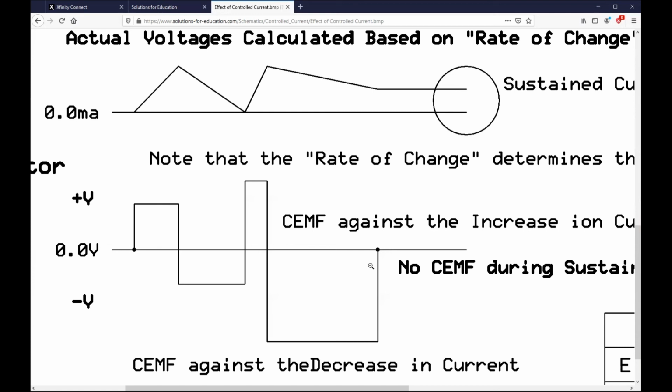There's some pinpoint or multiple pinpoints where it's a resistor for a tiny area on the aluminum, and the current flowing through there will heat up the inside of the capacitor, I squared R, and eventually boil that electrolyte, and it expands. And if that capacitor is built without a pressure release mechanism of some sort, it'll put up a lot of pressure and literally explode.